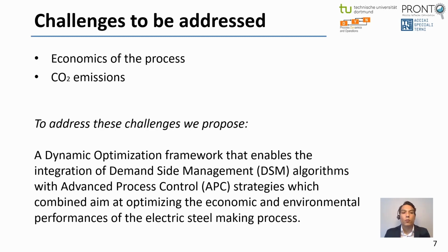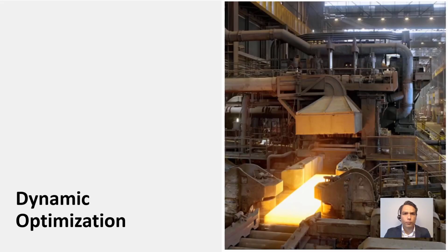And on the other hand, we have the CO2 emissions, which are of big concern in the current times. To address these challenges, we propose a dynamic optimization framework that enables the integration of demand-side management algorithms with advanced process control strategies, which combined aim at optimizing the economic and environmental performances of the electric steelmaking process.